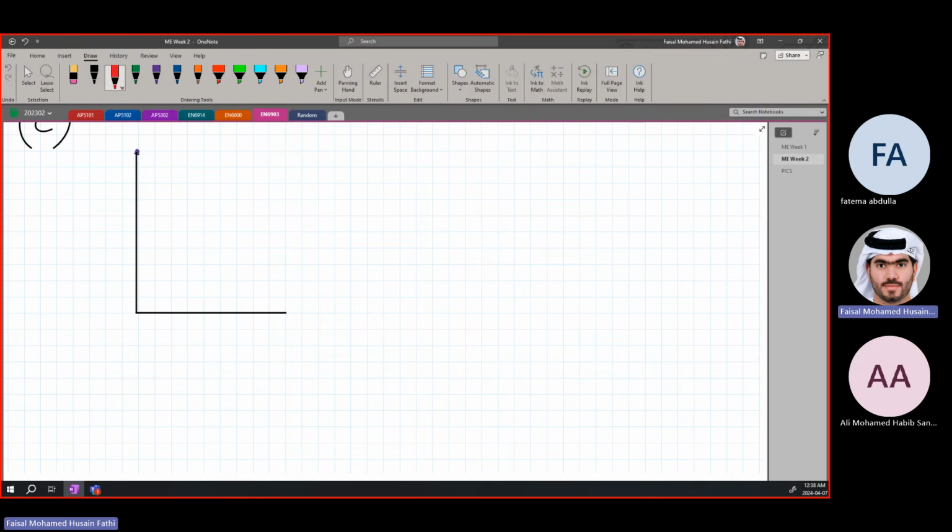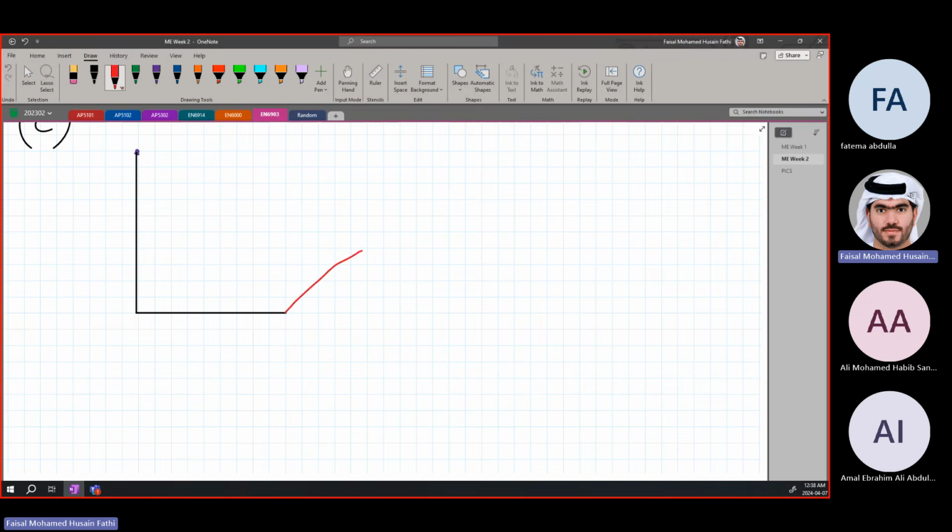We now want the force to be in this direction. Alright? In this direction. Why? Because we want this distance over here to be perpendicular. We want the full force to be perpendicular to this. It can be like this, or even the force in the other direction. It doesn't matter, because they didn't say they wanted a specific clockwise or counterclockwise moment. They just said they wanted the maximum possible moment.